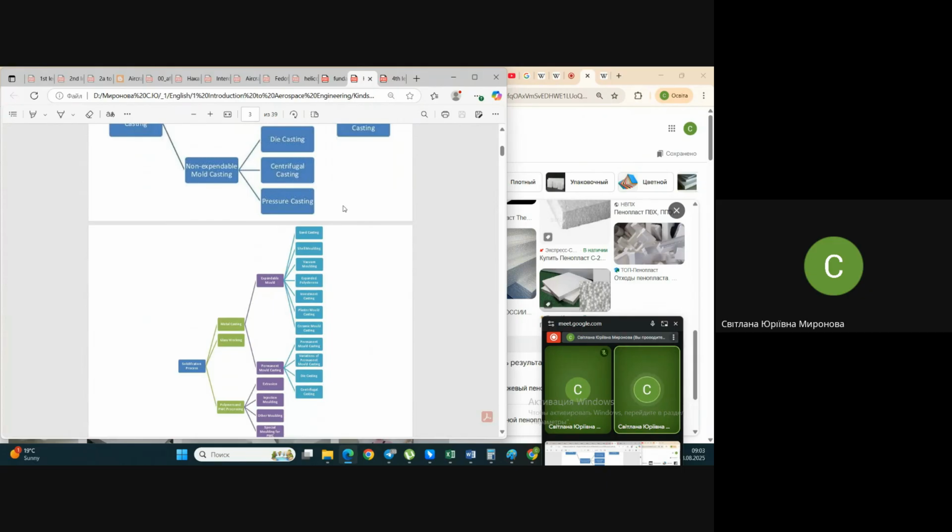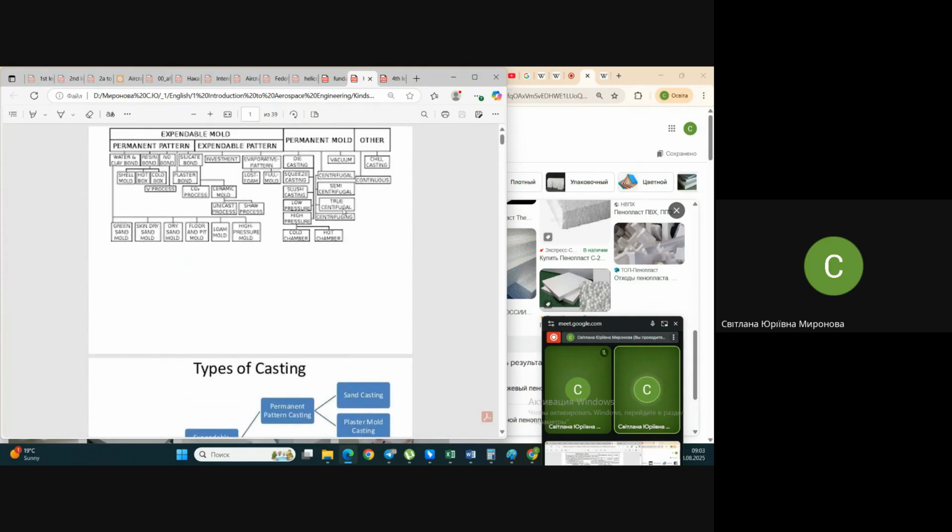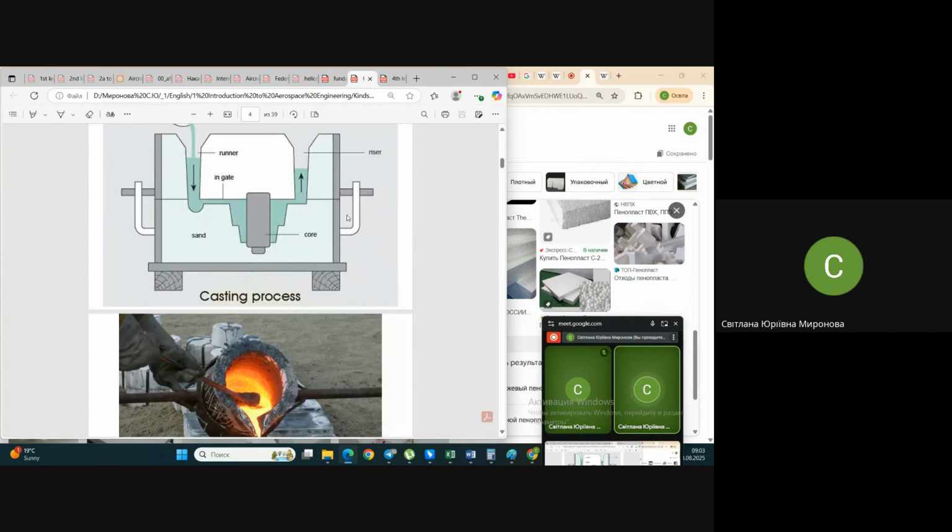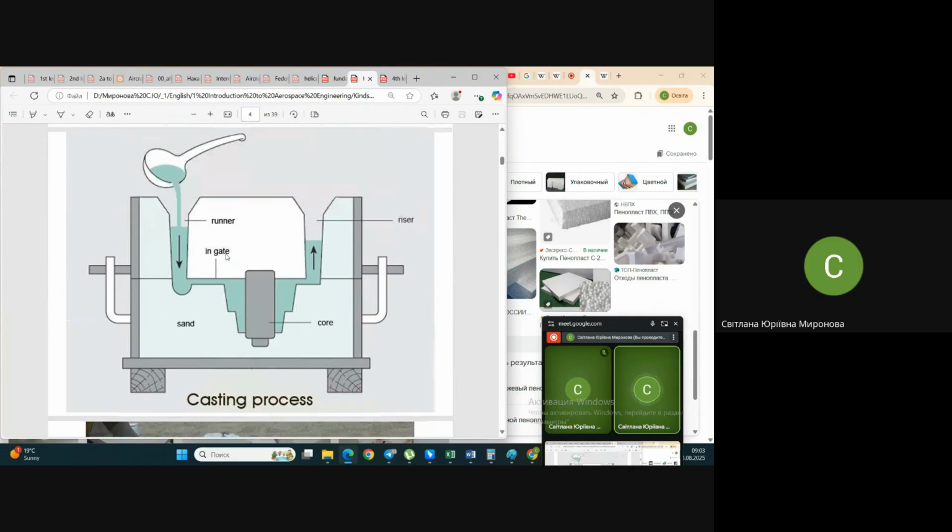What is it made for? Forgive me, another side of scrolling. How do we make the inner cavity in case we use, for instance, the sand casting process or some other process like this? Inside the ready mold, some solid element is inserted which prevents the material from filling this area, and due to this, a hole appears in the ready part.